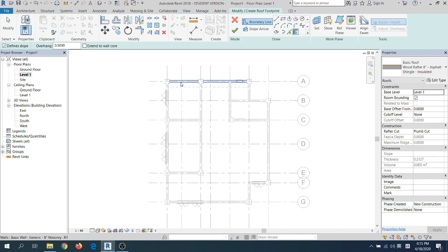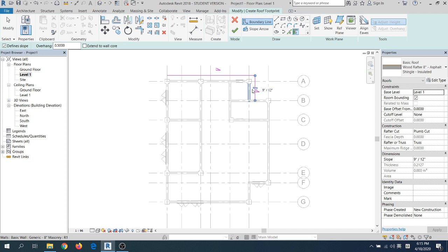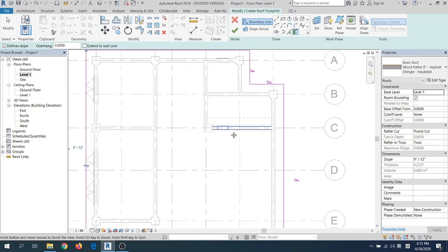So I just point to the wall I want, and there is a dotted line indicated there. So I just click it accordingly. I use the external wall as a reference line to create the roof itself. I click all the external walls and I found that the roof line has been created correctly.